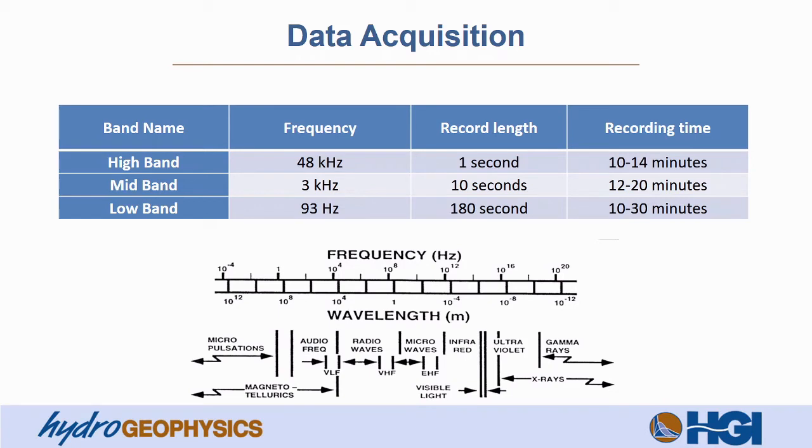The long wavelengths do not attenuate near the surface, yet provide decreased imaging resolution. The higher frequencies, and thus shorter wavelengths, help the user to see shallower with greater resolution. The short wavelengths attenuate at shallower depths, and thus the increased resolution is a trade-off with depth of investigation.